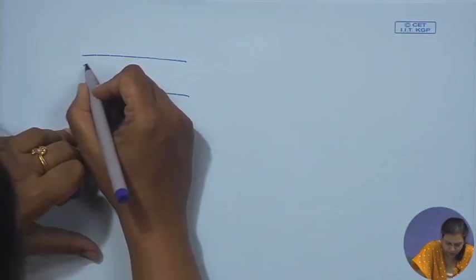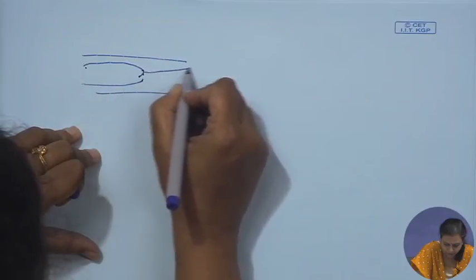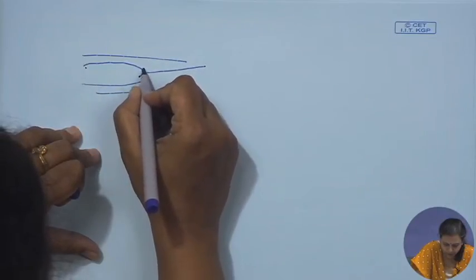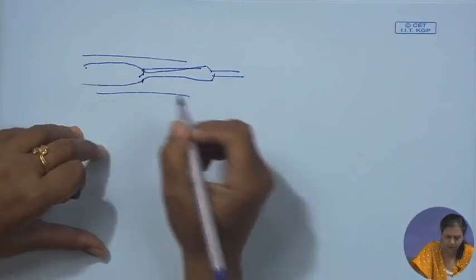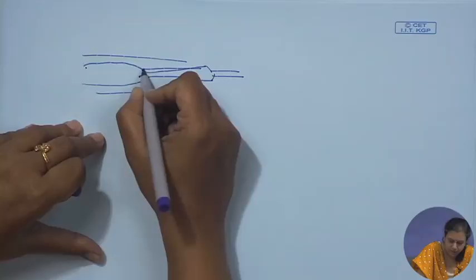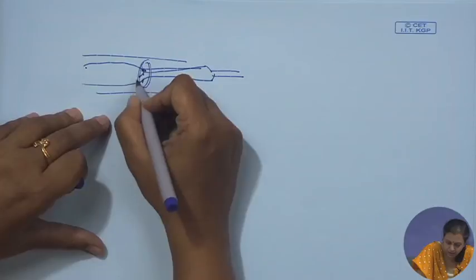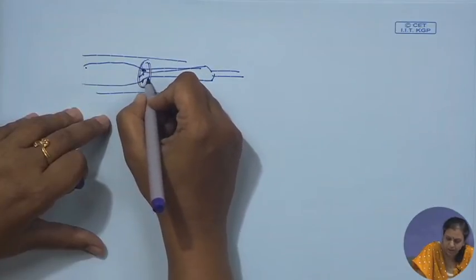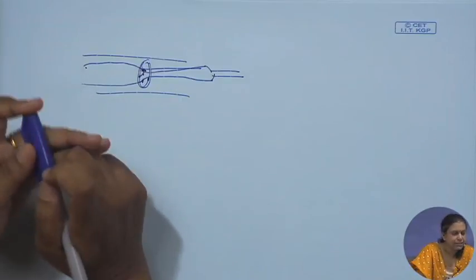The gas core, there are large bubbles here, there is a small necking sort of a thing and it goes in this particular way. So there is a gas core which is possibly continuous, but there are very short liquid slugs, and these liquid chunks form a bridging or a necking sort of a thing. It is better called necking than bridging, and this also people do not know whether it is slug or annular. So they call it a churn flow pattern.